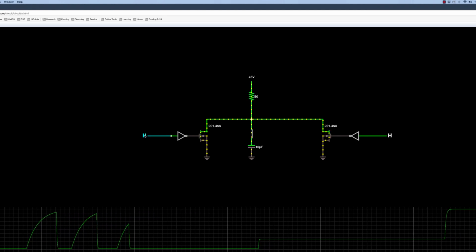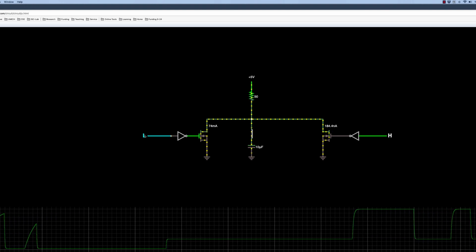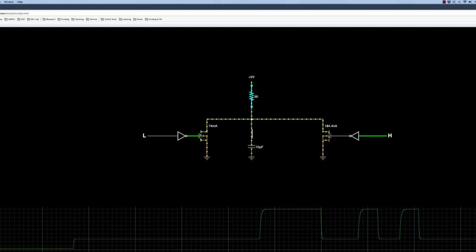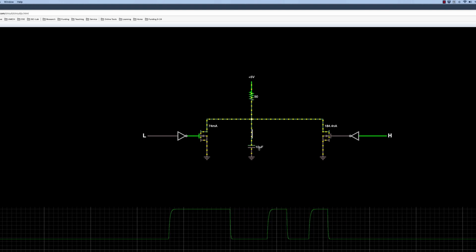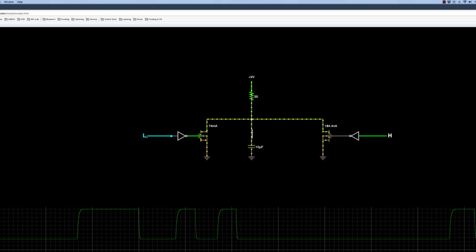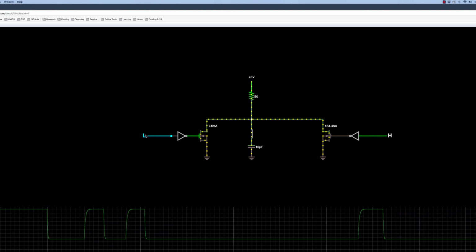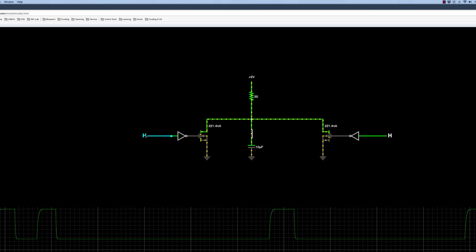All right, there we go. Up, down, up, down. In fact, we even see some errors because the resistance is so low and there's some real source resistance here. Most likely this is going to be nanofarads or picofarads. But anyways, it's important to realize that capacitance is what's slowing you down, and you need smaller and smaller resistors, which can drive more and more current, if you want to go faster.